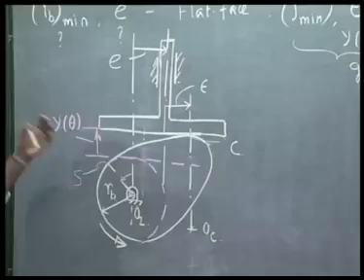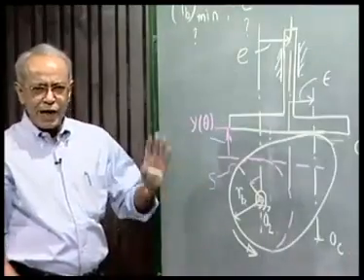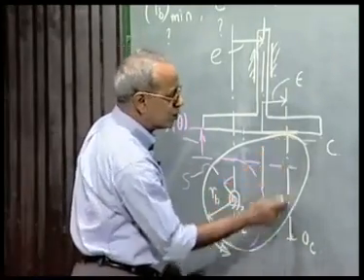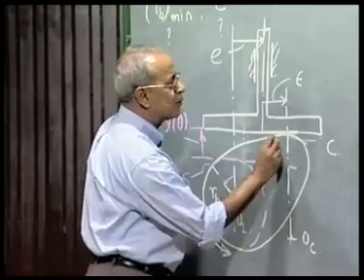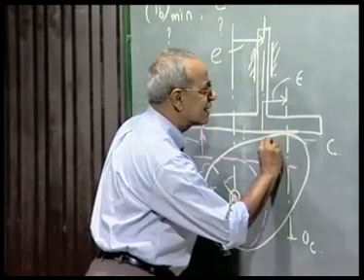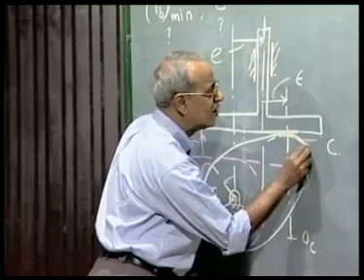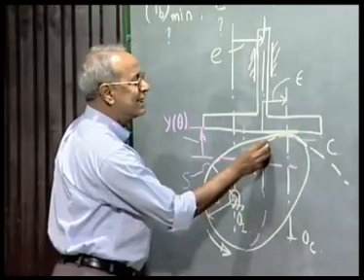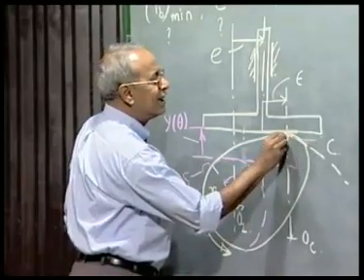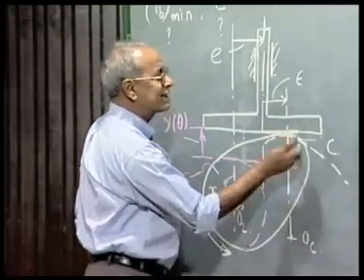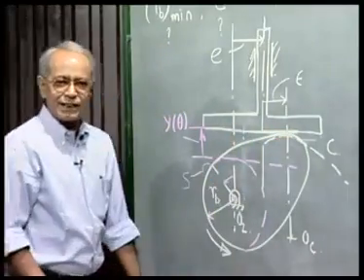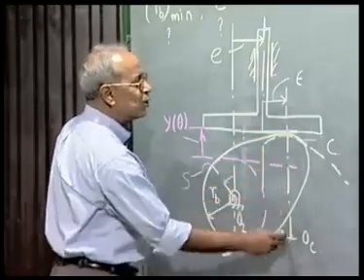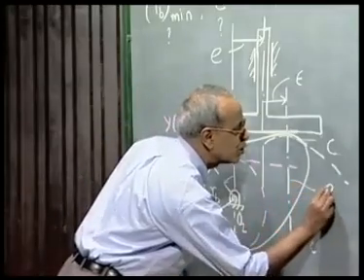For 3 infinitesimally separated time instants, the circle with center at OC and OCC as radius is the same as the cam profile. So if I draw the circle with OC as center and OCC as radius, then this circle and the cam profile, at 3 infinitesimally separated positions, are the same.